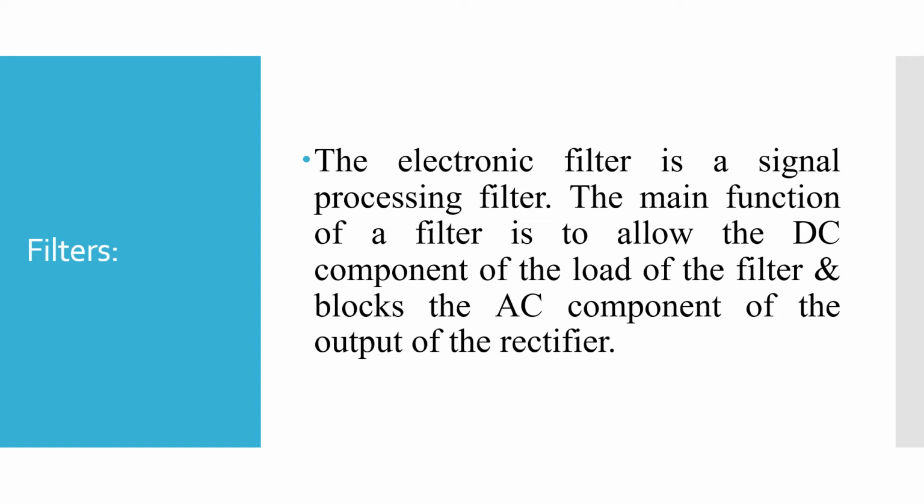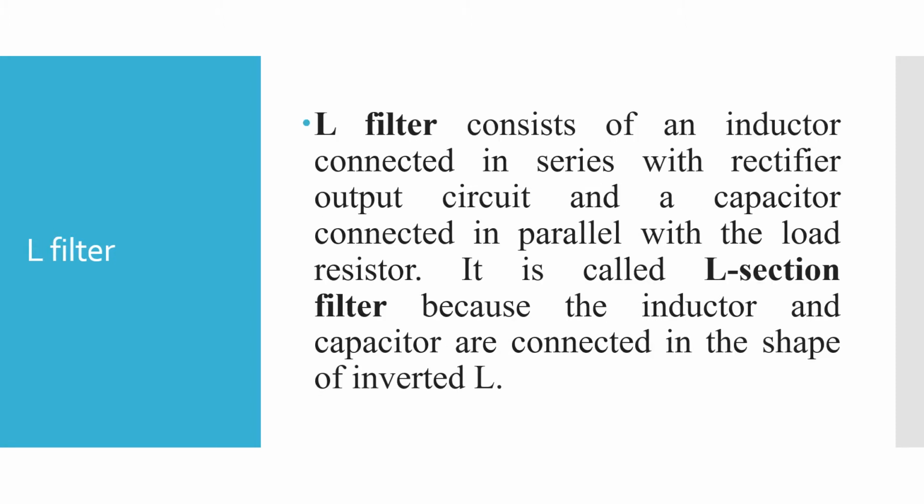Let us see the L-type filter. This L filter, or L-type filter, consists of an inductor connected in series with the rectifier output circuit and a capacitor connected in parallel with the load resistor.